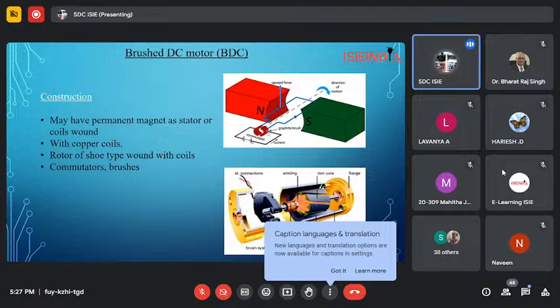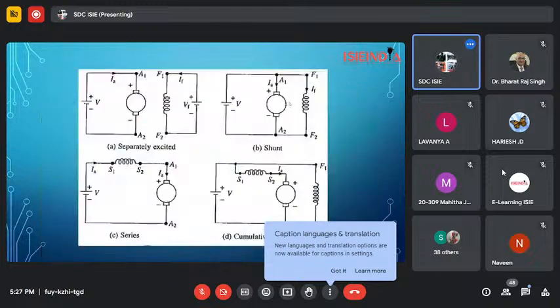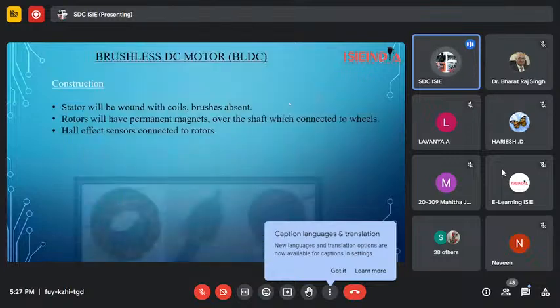But in electric vehicles, if we use these motors and there is any kind of gap there, water will enter or the dust from the roadside will enter the commutator and inside the motor. So obviously the efficiency will reduce. There might be short circuits or anything might happen there. So what we need to do here is remove that commutation.